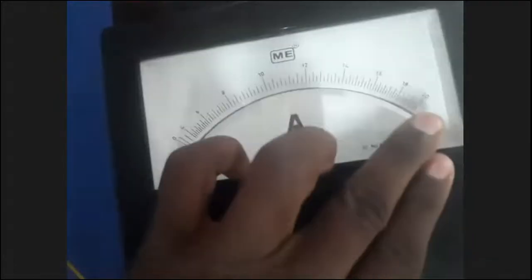See, here it is reading, as I have connected it to 10. So in between 0 to 2, there is one line, and between 1 to 2 there is again one division. That means here it is 1, 1.5 and 2. So it will show near about 1 ampere. So this is the 10 ampere current. Again, this will also show some reading, but this voltmeter I have used for high range. It is nothing but 20. This ammeter can be connected near about 20 ampere range. So it will show very little deflection, right?